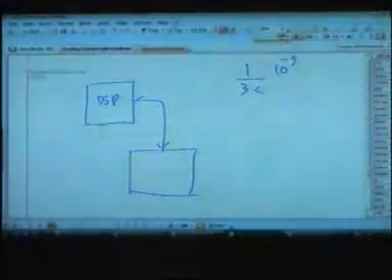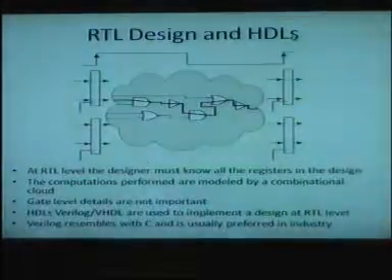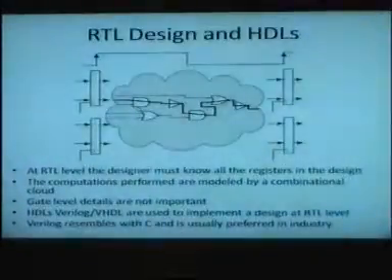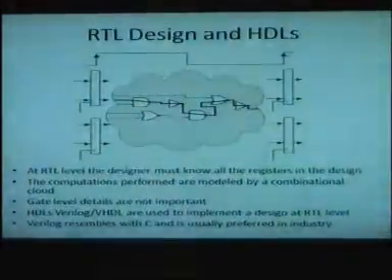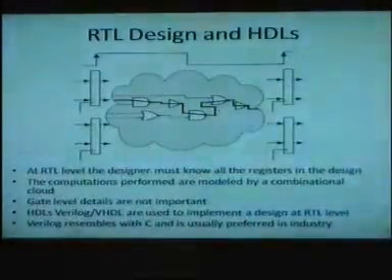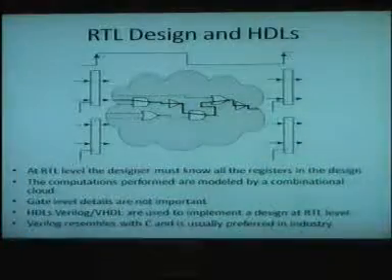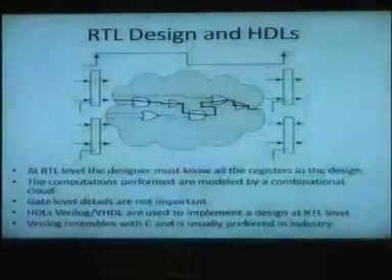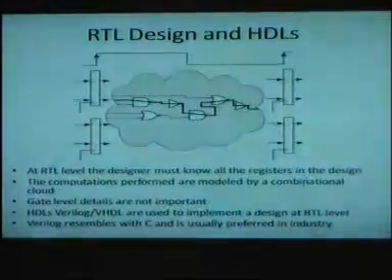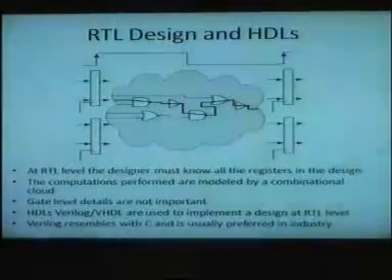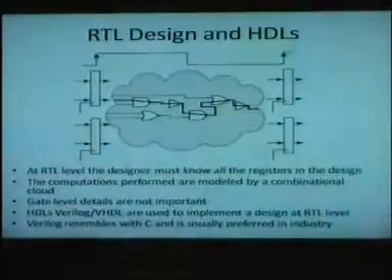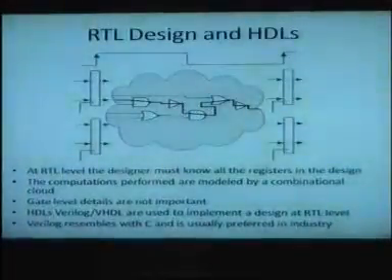So all the gates, as the slide shows, the combinational logic is made up of gates, and you are not worried about what gates and how it actually gets implemented, but you need to understand that combinational logic consists of gates, and every gate has a delay, because gates are made up of transistors, and every transistor, once it switches from 0 to 1, will take some time. So many transistors in a path will take more time, because unless all the paths in the design are settled, as we show, this is the longest path.